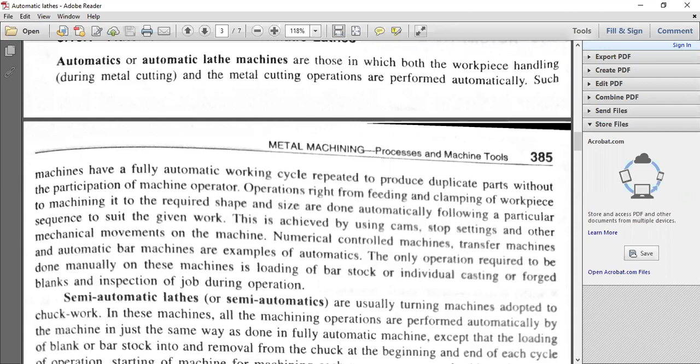So we have the other drives to control the shafts, known as the back shaft drives, and others, because already we have discussed in Unit 1 the coolants or the cutting fluids or the lubrications. We have the lubrication units, because they are very important to control the temperature of the workpieces. The dimensions of the workpiece are affected by too much heating, by too much friction between the workpiece and the tool. So all these are very important parts of the single spindle automatic lathe.